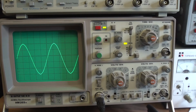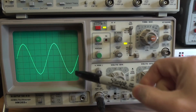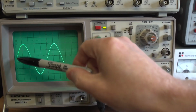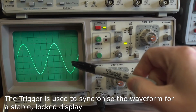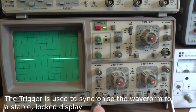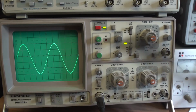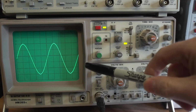And one thing worth noting about oscilloscopes is the triggering, and that's what allows this trace to be almost looking stationary. It's not flying all over the place. It's synchronized. The dot is actually synchronized, so we can see a continuous wave locked on the screen, almost like it was a storage scope, except it's not a storage scope because if we disconnect it, it goes away. There's our signal. Put the signal back on. There it is. But it looks almost like a storage scope. It's not flying to the left or flying to the right.